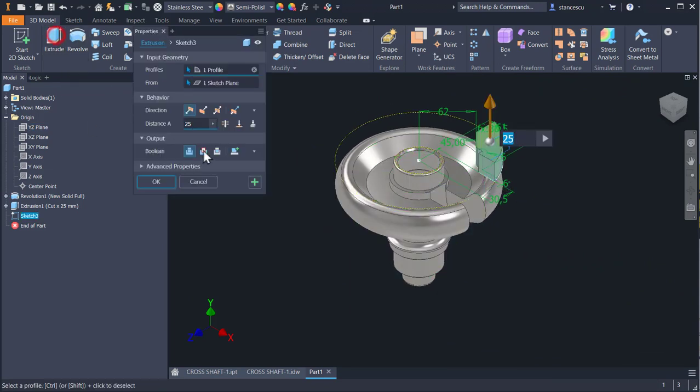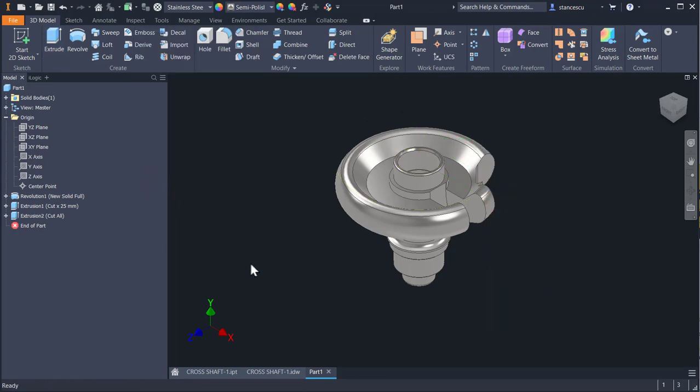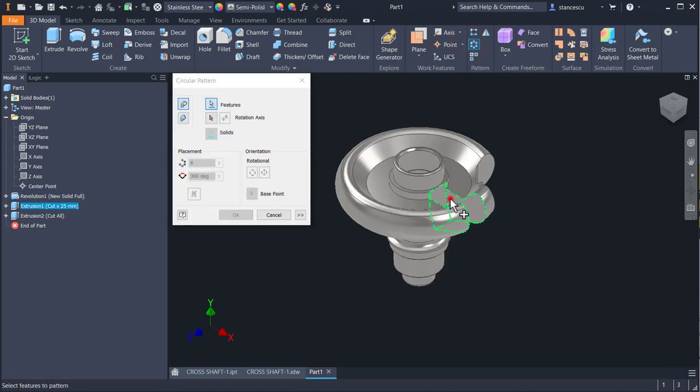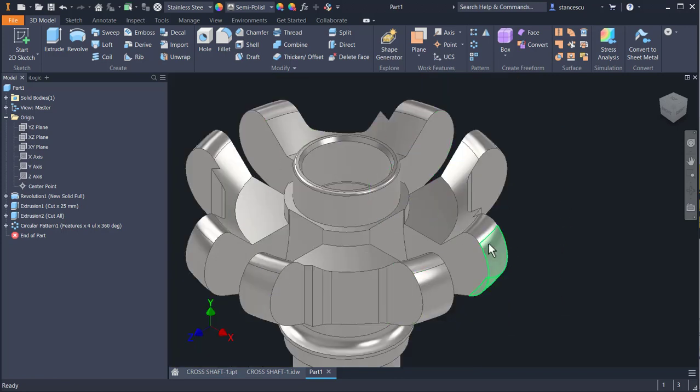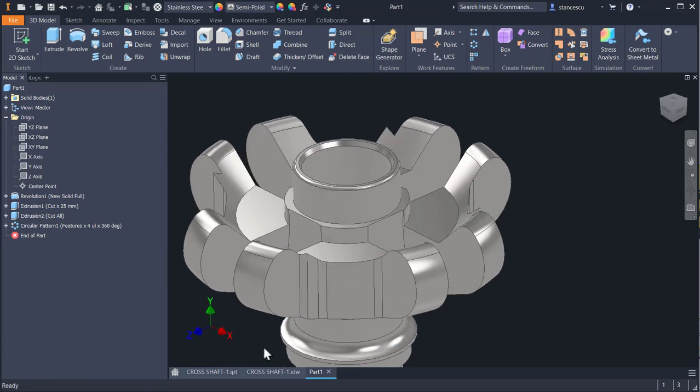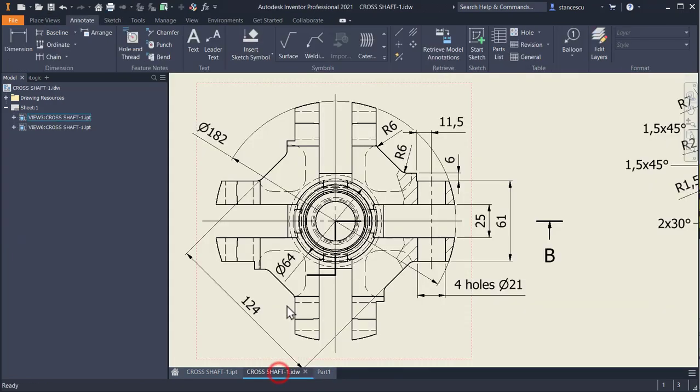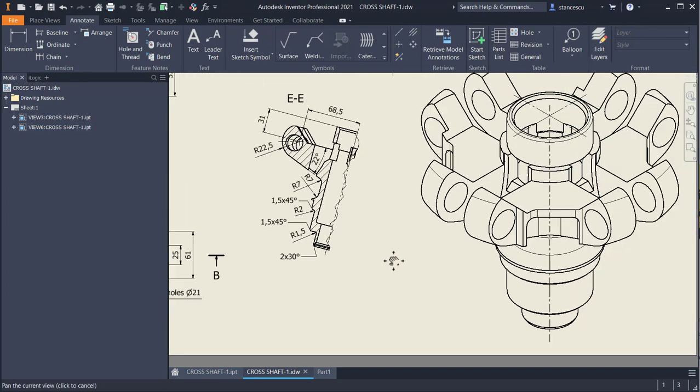That's all. Extrude, cut all the way down. Okay, now I apply a circular pattern for these two cuts. Yes, about this axis, 4 instances. Okay, you see that face, but this is round, and you see here that the face is not round at all.